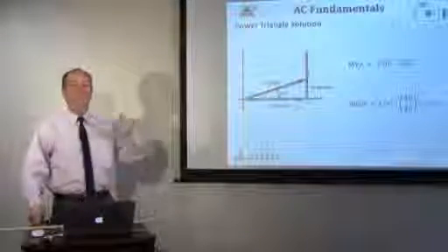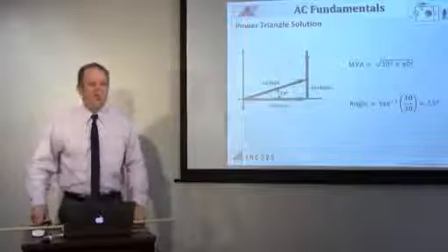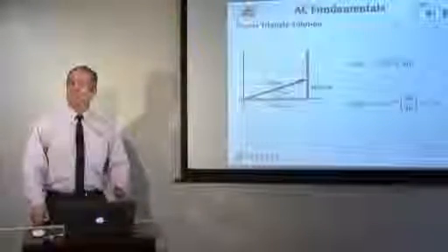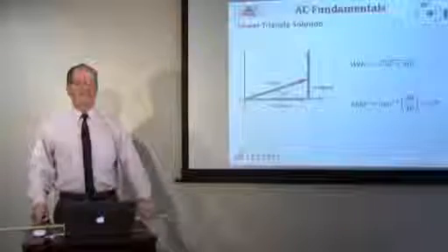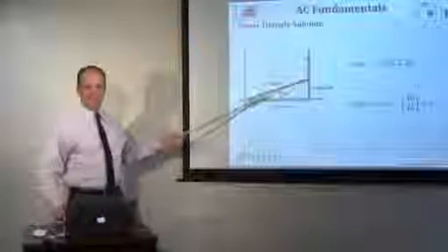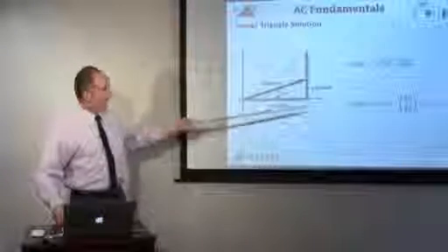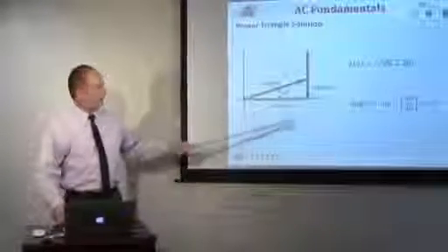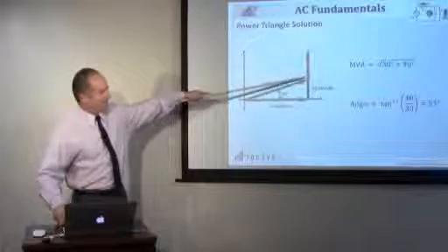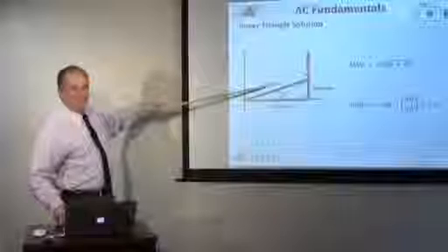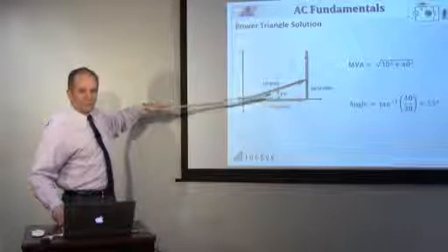Their revenue meters, or kilowatt-hour meters, don't really turn for VARs. They're watt meters, not VAR meters. So if they invested in a 50 MVA transformer, they'd want to put 50 megawatts through it, not 40 megavars. So they would add capacitors to bring that number down, so then they could have 50 megawatts for a 50 MVA transformer. Now they're making money.